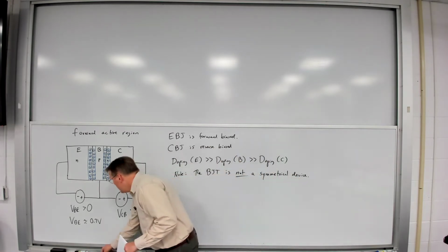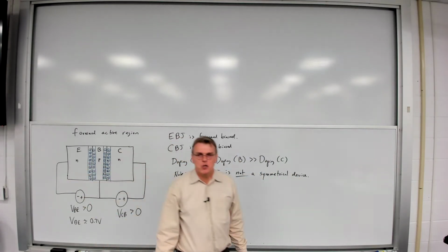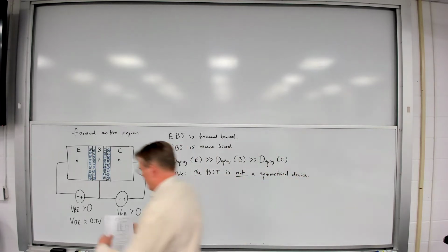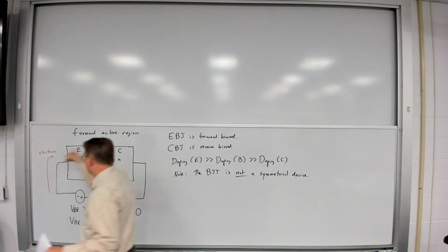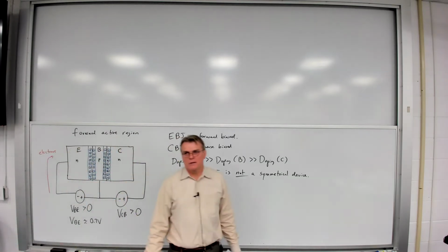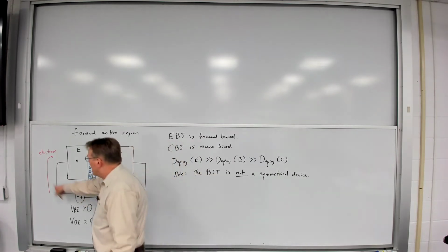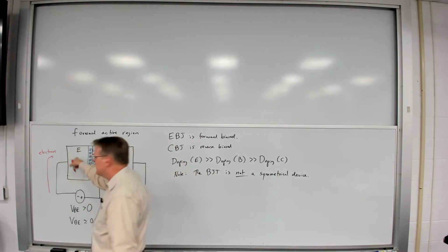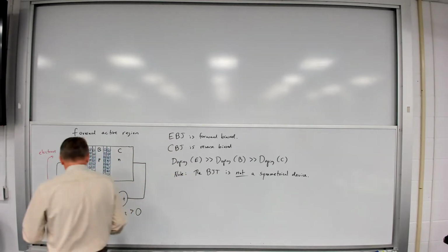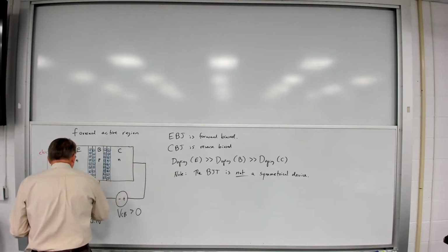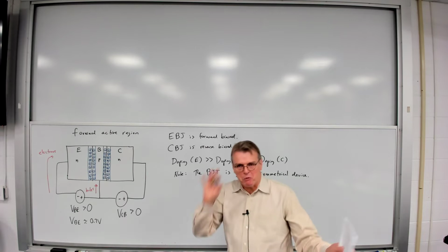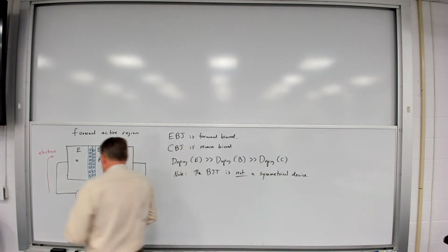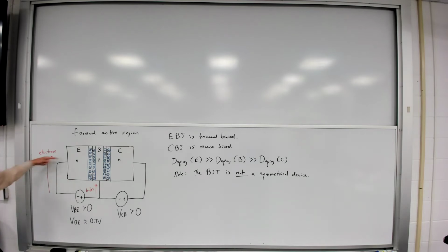First of all, let's focus on this forward biased junction between the base and the emitter. So there's going to be current flow. It's a forward biased junction. And in this case, electrons are going to flow out of the negative end into the emitter. Holes are going to flow, and once again, we are thinking of holes as if they were positively charged particles. That's just the way we would create that mental model. So holes are going to flow in this side, electrons are going to flow into this side.